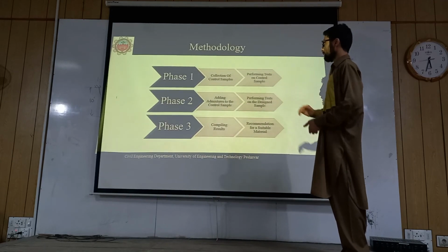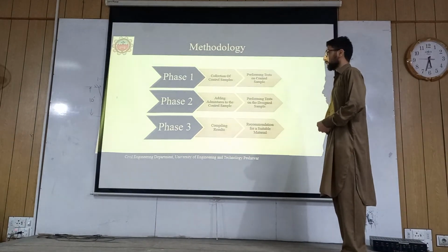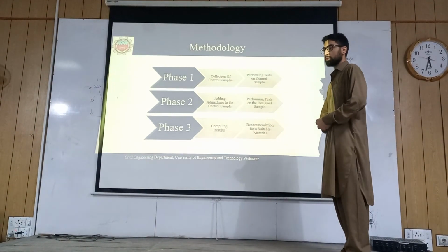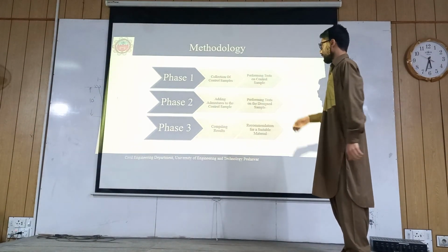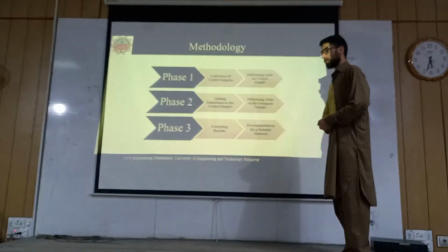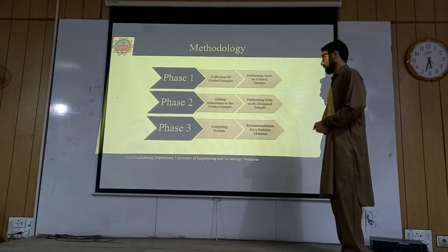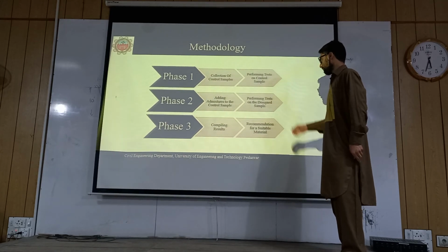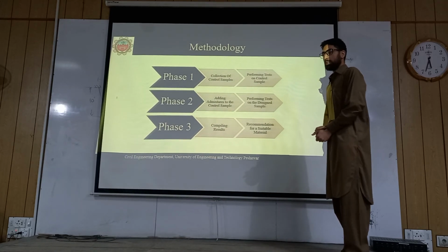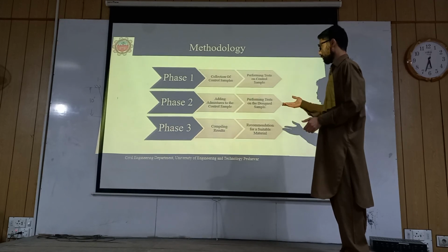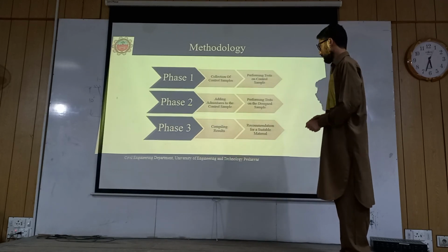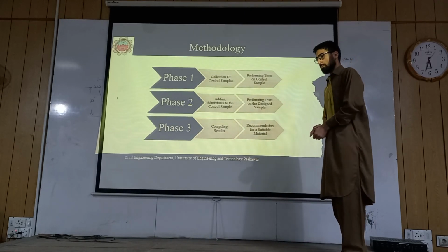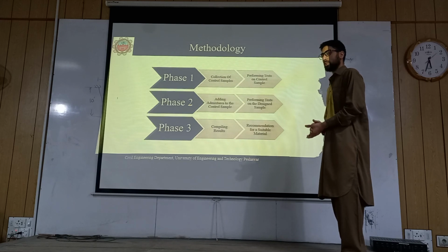This is the methodology. In the first phase, we will collect control samples from the waterlogged areas, then perform tests on those control samples. In the second phase, we will add mixtures to those samples, then perform tests on the design samples. After that, we will come to know the results. We will recommend a suitable material for that place, which is locally available and economical as well.